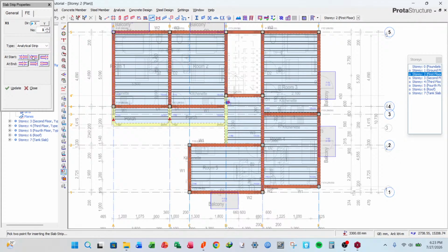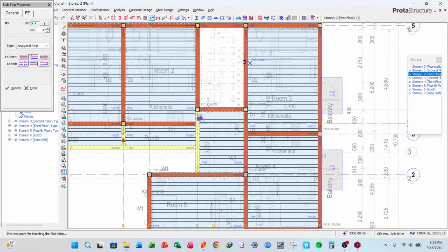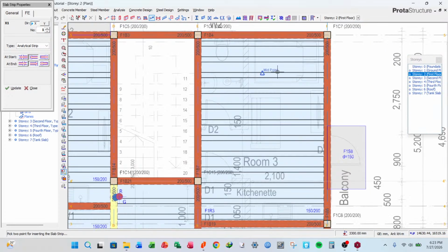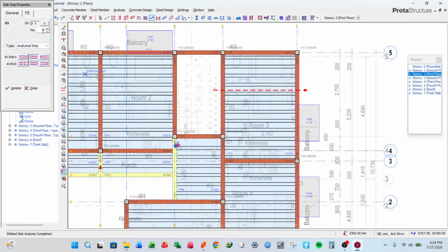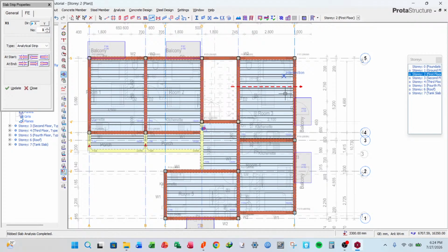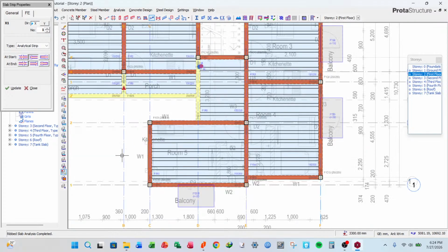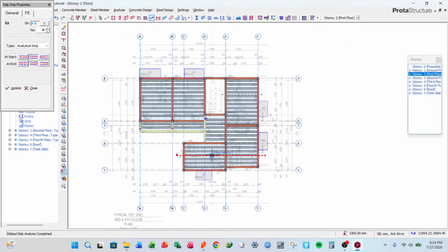So let's first set end to end non-continuous, because this panel is not continuous on either end. So we shall do strip, press Ctrl to make it horizontal or straight. So this is strip x1, as you can see. I'm going to draw another one here, same end conditions. Press Ctrl like that.